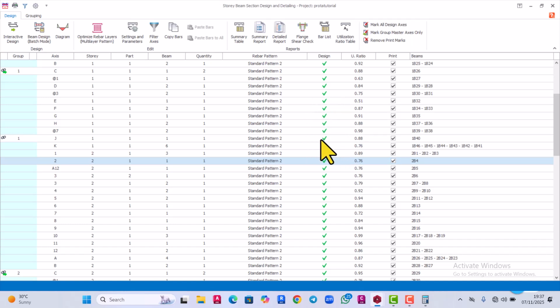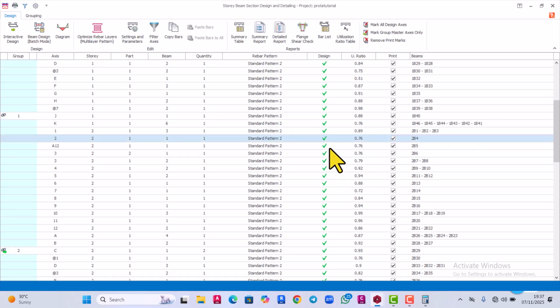Because sometimes this software uses a reinforcement of 20 mm for your beam, but you discover that 4Y16 can actually do that, or even 3Y16 can do that most of the times. And that's why they say software is garbage in, garbage out. You are left to be the structural engineer you are meant to be. So we are going to go into those beams one after the other to make sure that the detail we are generating is based on structural engineering judgment.